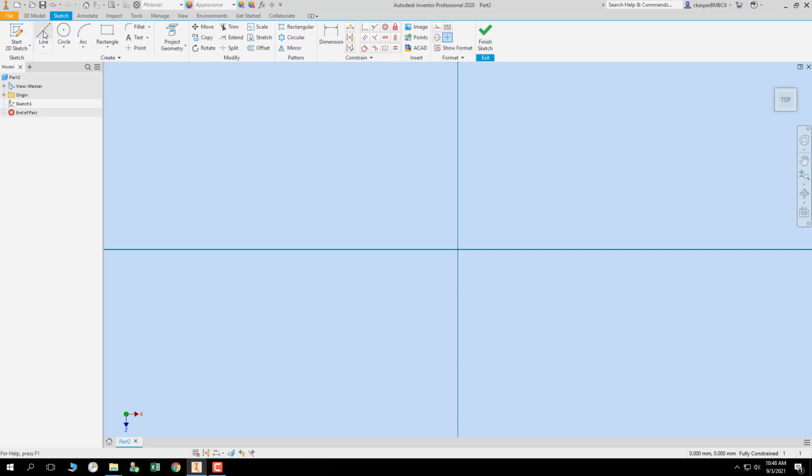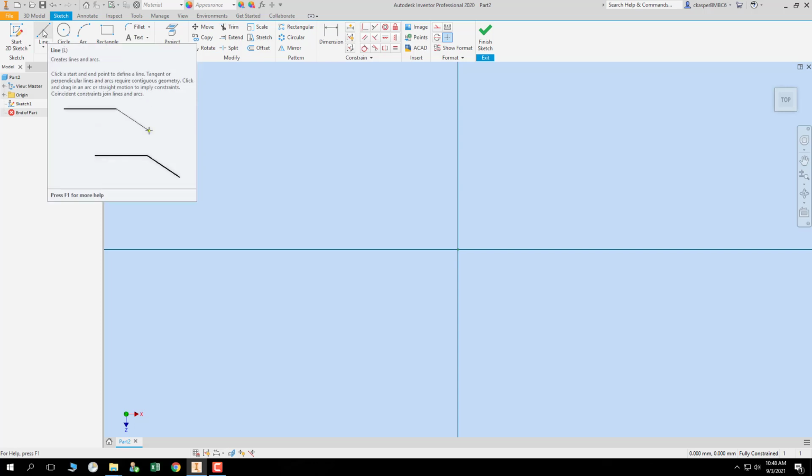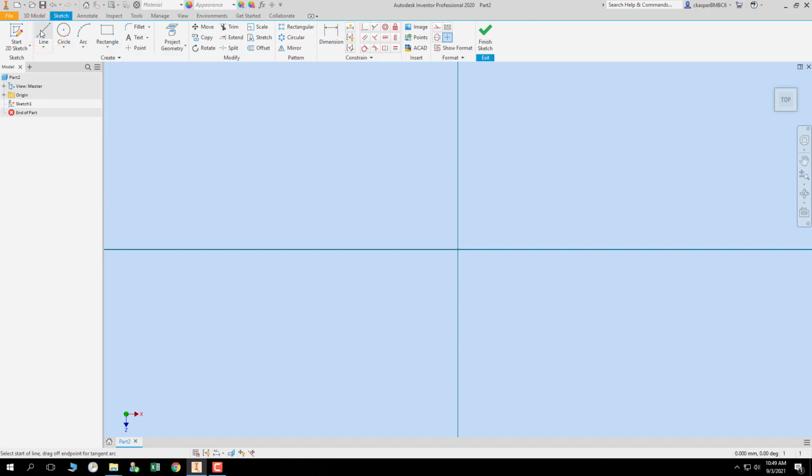Let's start drawing a line. Now a lot of these commands are what they call chained. They create chains, and I'll demonstrate what that means. I'll click on it one time with my left mouse button, and now I'm locked into it. You can see it's got the focus. I have a yellow dot on my screen, and of course I have the X and Y coordinates it is showing me, but I kind of ignore those, and here's the reason.